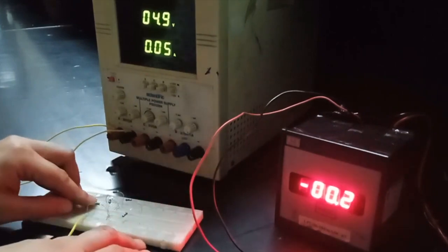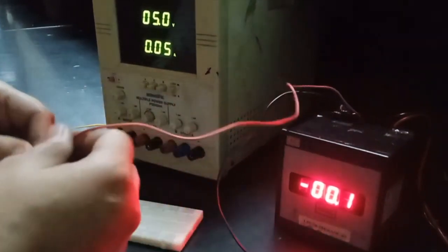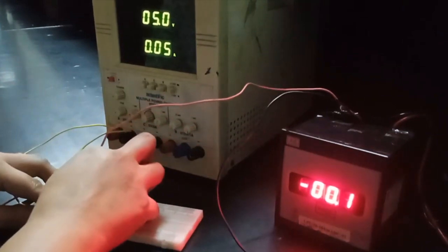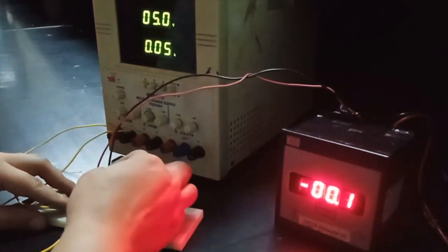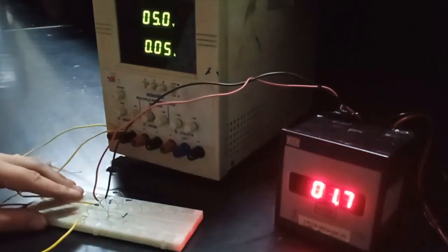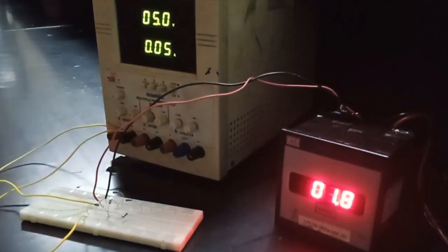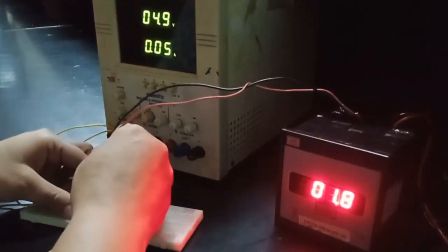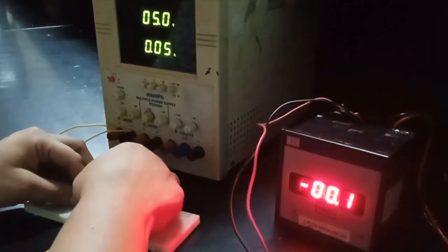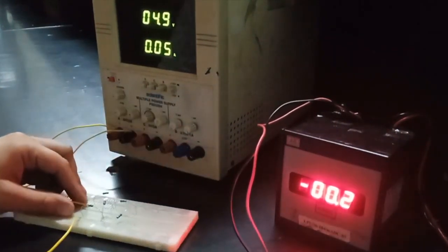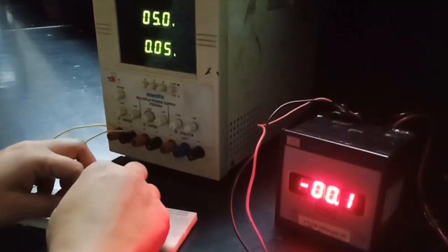So I have broken one connection and now we are supposed to connect the ammeter in series. So the positive of the ammeter with the positive of the supply and the negative of the ammeter with R1. So here comes the value of the first current I1, that is equal to 1.8 milliampere. Second, I2, but for that remove the ammeter and do not forget to restore the previous connection. So I have restored the previous connection. Now let us calculate I2.